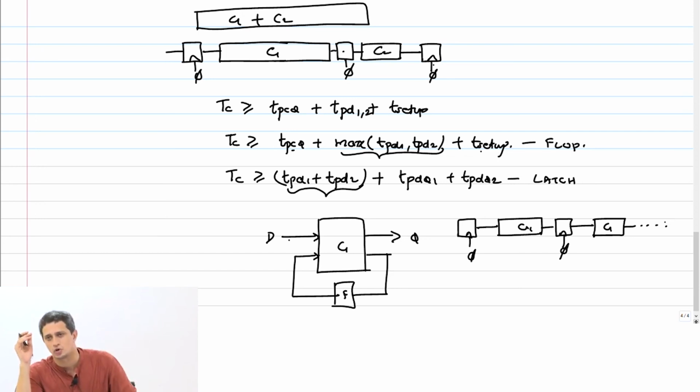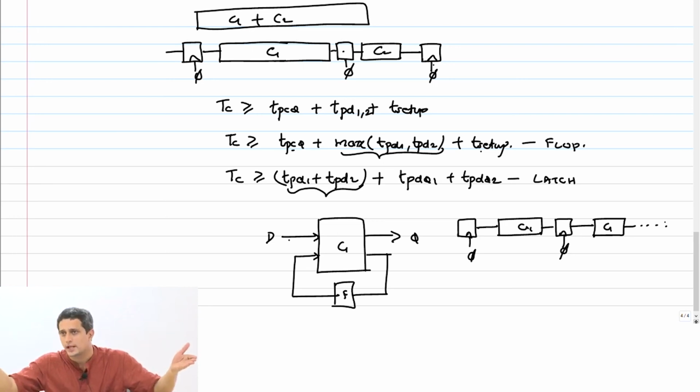Now if I put latches also here, the same C1 is repeating over and over again. Which means what I told you earlier is not going to be possible. You can do time borrowing if one block takes time, provided the other block is short enough to finish early. But if it's the same block that is repeating again and again, there's no question of faster or slower. At some point you're going to violate if I borrow across the boundary. So the way to analyze these feedback systems is to unroll it in time and then see what happens.